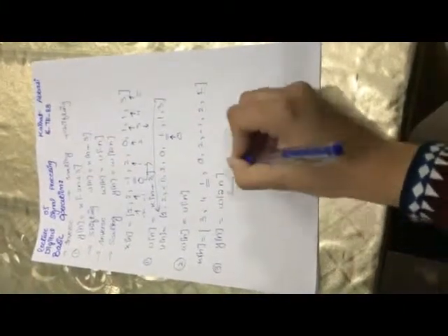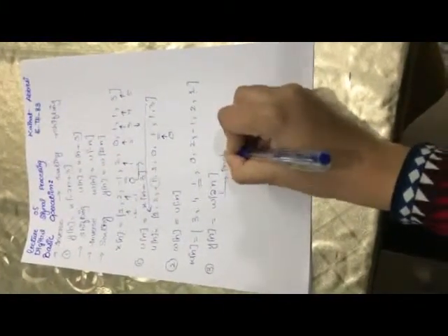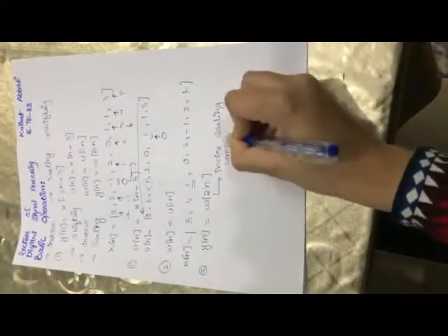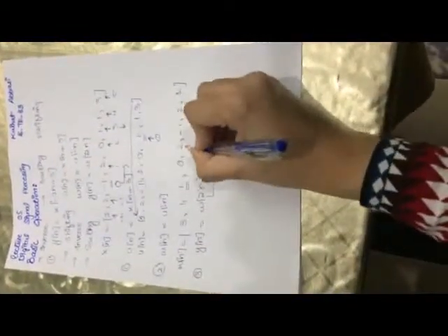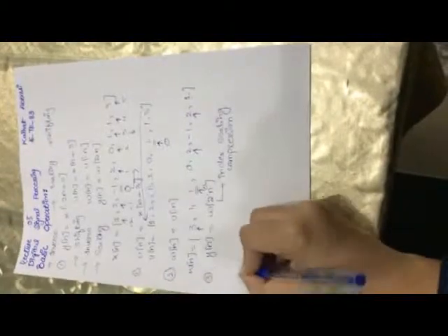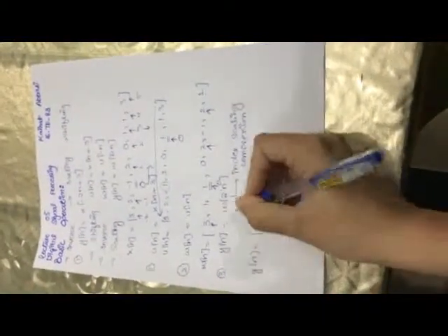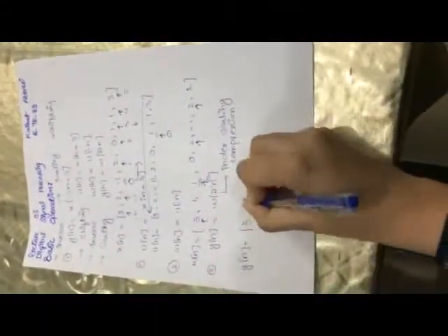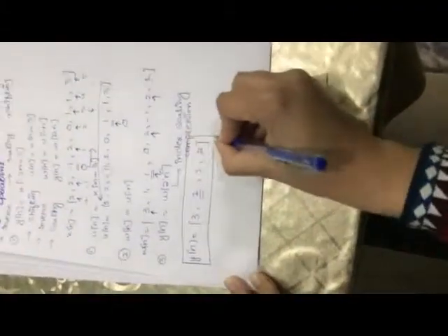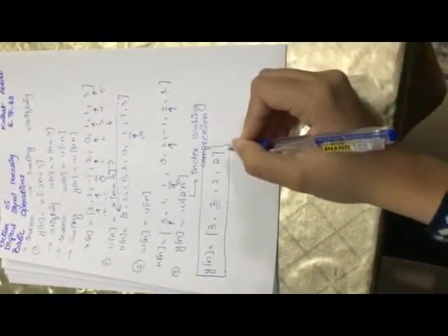This is index scaling. And multiplication here indicates compression, that is our original system is compressed 2 times. That is, this is 0th value, and after 1 point the values are retained. You can also verify this by putting each value 1 by 1. 3, 1, this is 0th point, 2 and 2. So this is our y of n after applying all 3 operations: shifting, inverse and scaling.